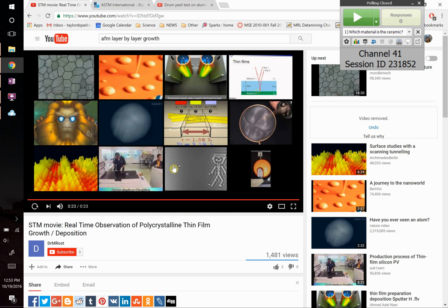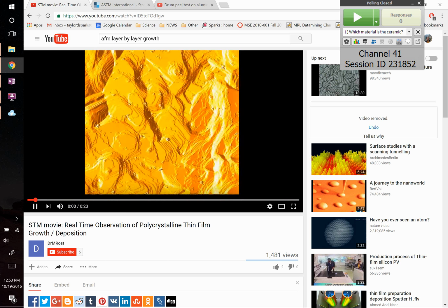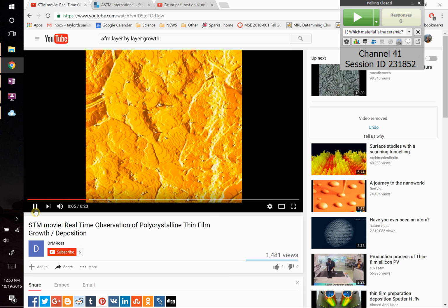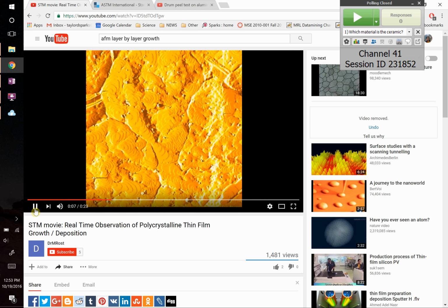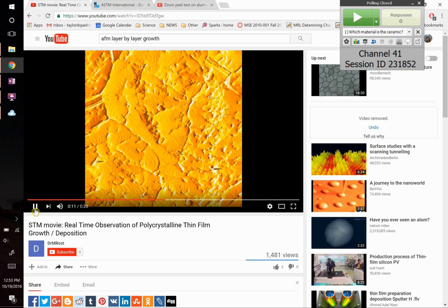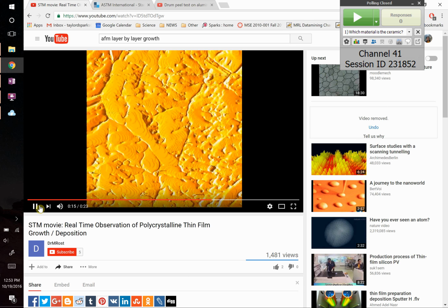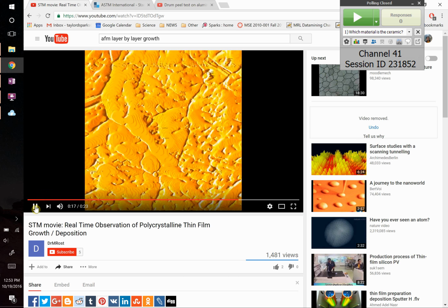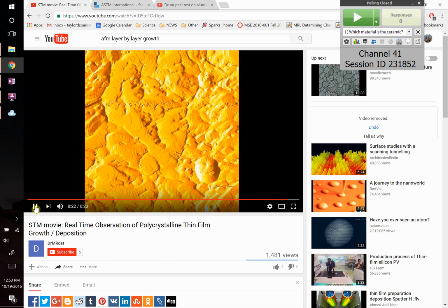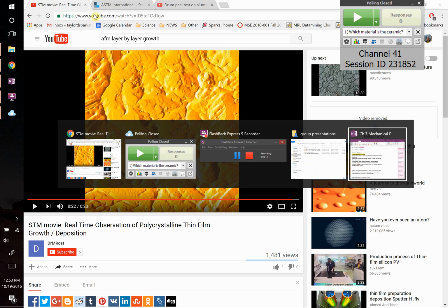If you do what's called physical vapor deposition sputtering, let's show that one more time. If you grow these things by just bombarding a surface with atoms, they could sit just anywhere. They could just sort of speckle it like spray paint would. But if you do it by giving it a little bit of slow time and then giving it energy, do it slowly so it has lots of time, it's going to grow specifically by going on those ledges, which makes them a nicer, more uniform film. Okay? So there's that for today.